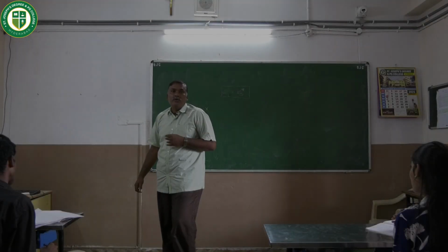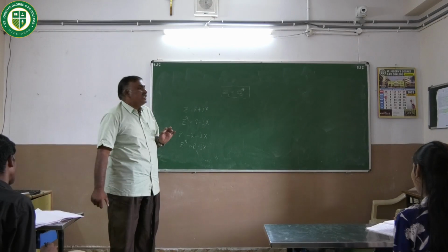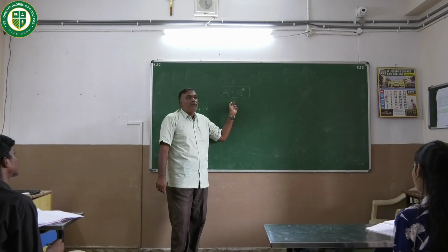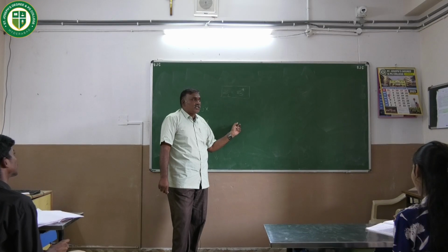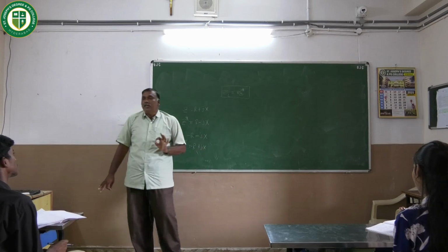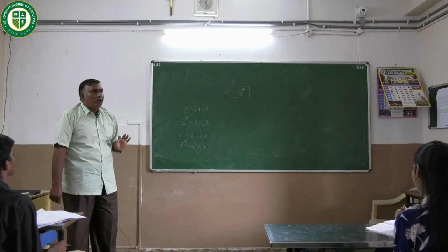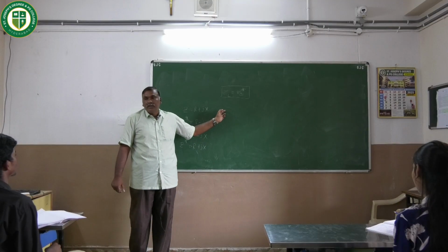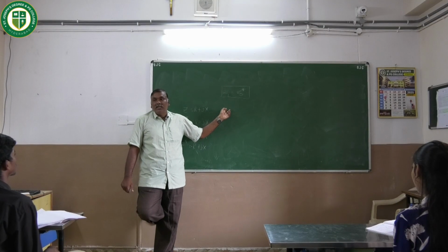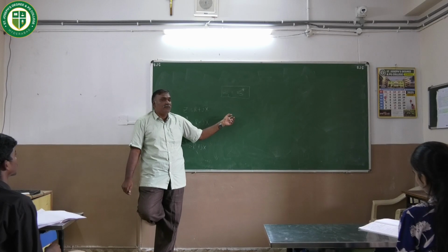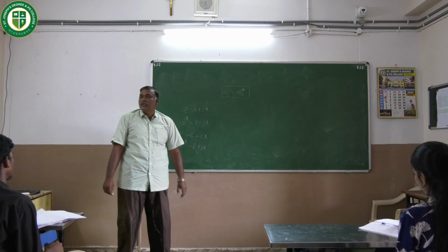Dear students, we are going to discuss today the maximum power transfer theorem statement, its application, and also the mathematical procedure to prove it. According to the maximum power transfer theorem, in a circuit or a network, the maximum power can be delivered from the source to the load when the load impedance is equivalent to the complex conjugate of the source impedance.